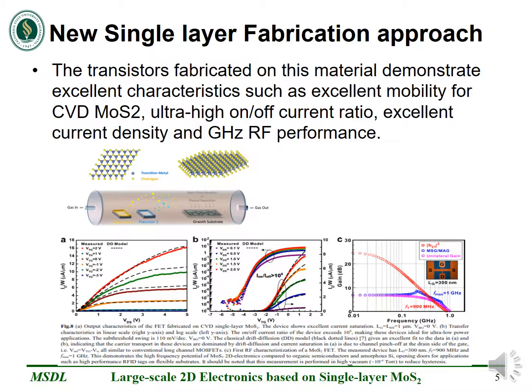As a 2D material, it shares many properties of the well-known graphene, such as excellent mechanical flexibility and high thermal stability up to 1090 degrees centigrade, with a better band gap of 1.8 electron volts. It also overcomes the key shortcomings of graphene for electronic applications, the lack of clear current saturation and pinch-off.